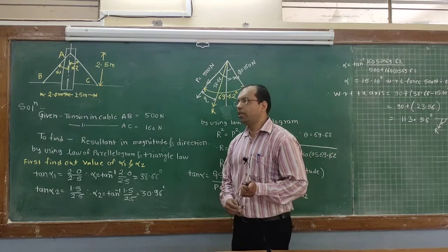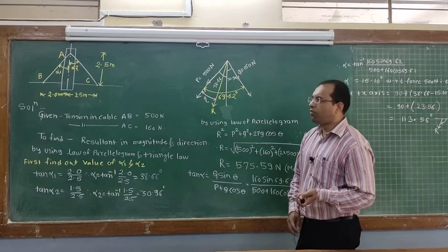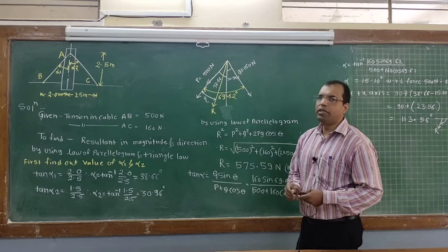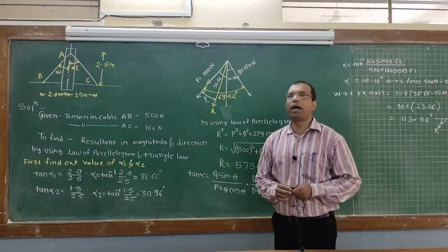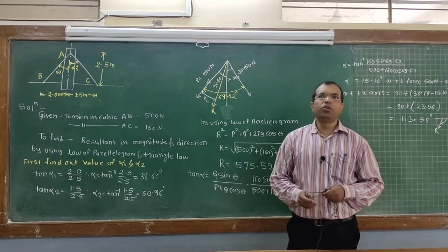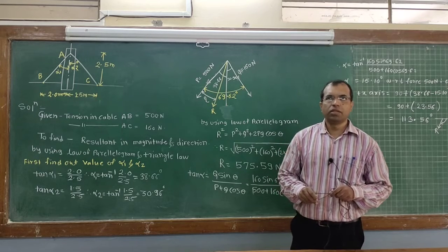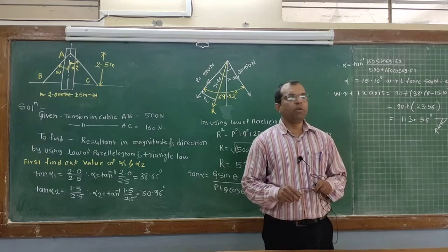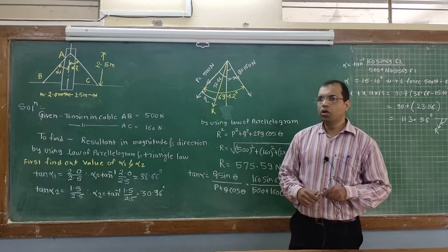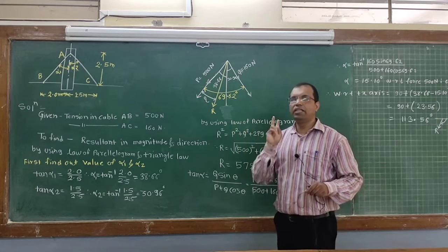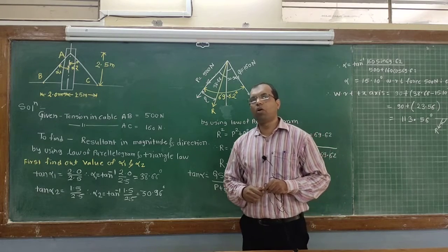Let's come to today's lecture. Today we are going to solve one numerical by using the law of parallelogram of forces and the sine rule, that is, the triangle law. When there are only two concurrent forces, we have to use the law of parallelogram of forces. The law of parallelogram of forces cannot be used if there are more than two forces. So care should be taken that only when two concurrent forces are given can we use the law of parallelogram of forces.